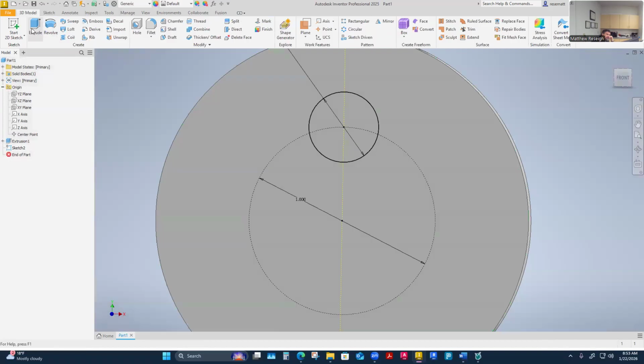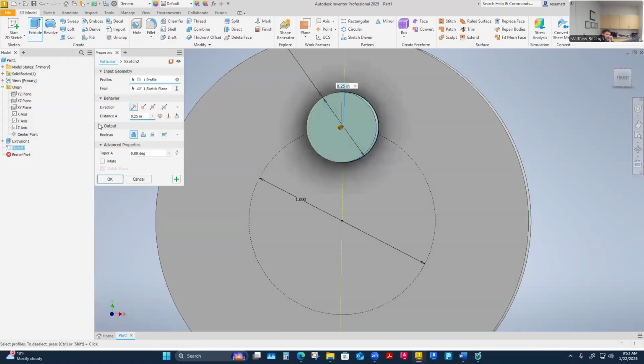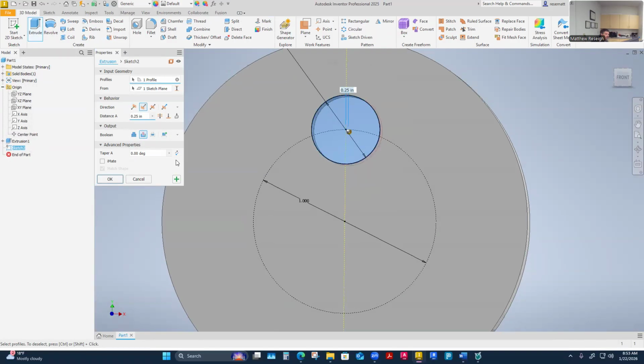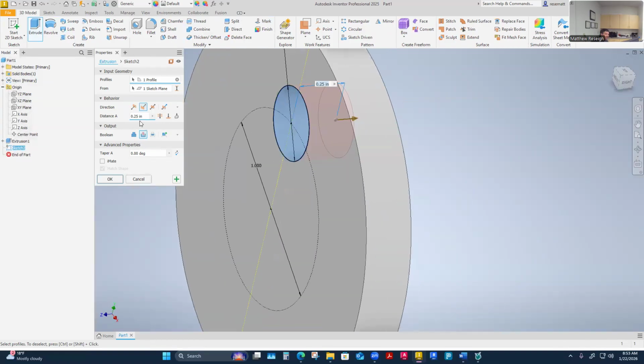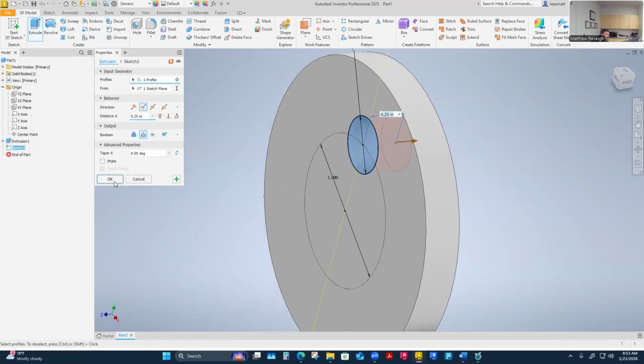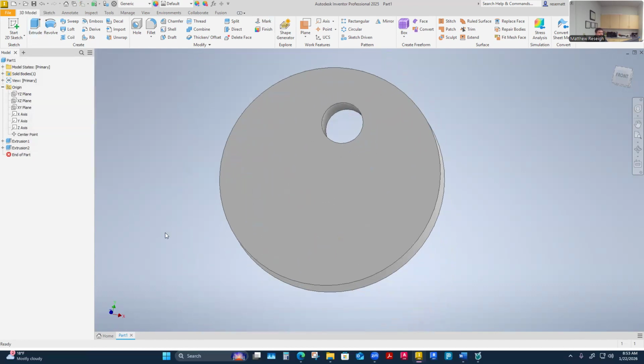This one's going to be an extrude cut. I think we just extrude cut this at a 1/4 inch dimension like that. So it's against how I usually do, which is through all. And then we actually just put in a 1/4 inch dimension. Yeah, those constraints are kind of... I could go into that sketch and even constrain it completely different.